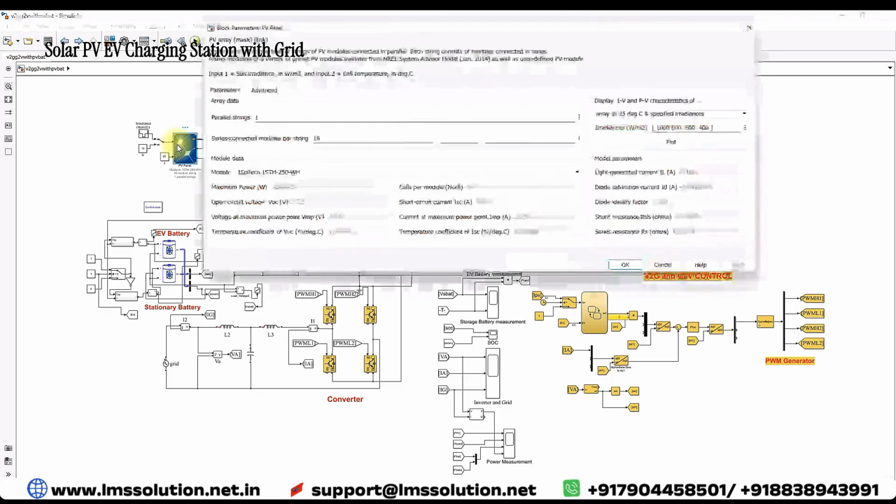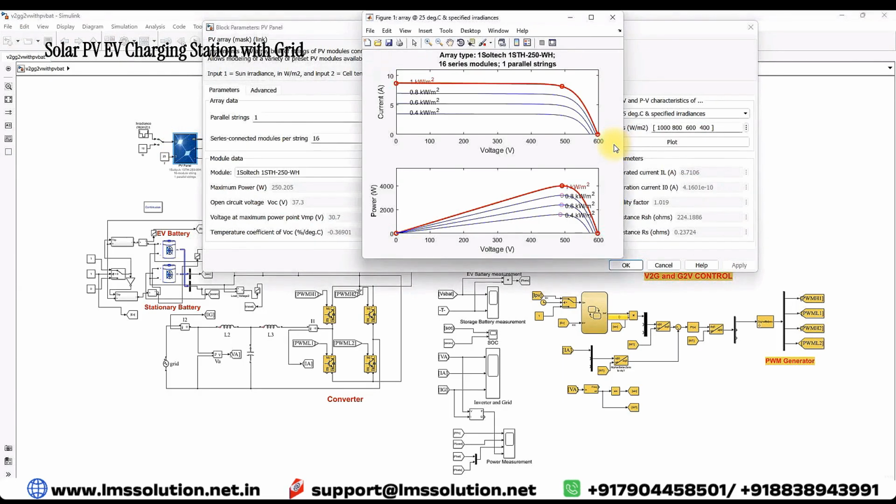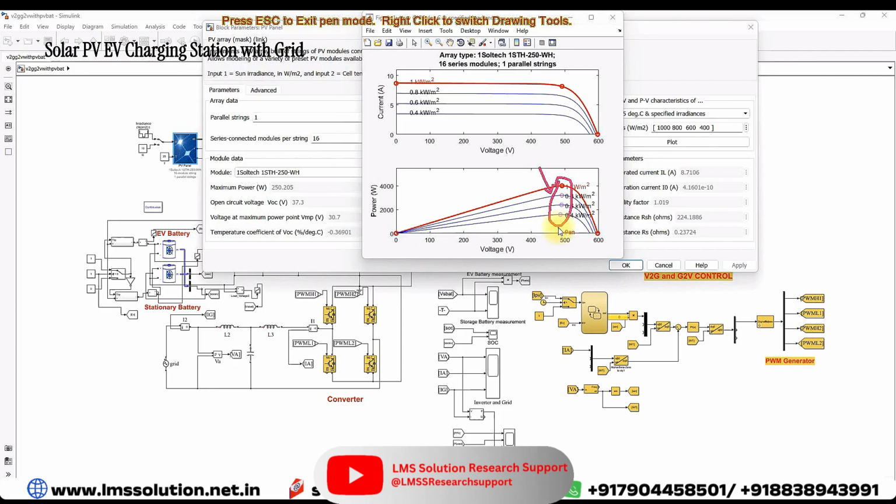Here you can see that for different irradiation conditions, that means different sunlight intensity conditions, the peak power of the PV panel will vary. We must track that peak point. In order to track that peak point, we need to use some control concept. The control concept is nothing but the maximum power point tracking algorithm. We are going to track the maximum power, and that is known as the maximum power point tracking control algorithm.